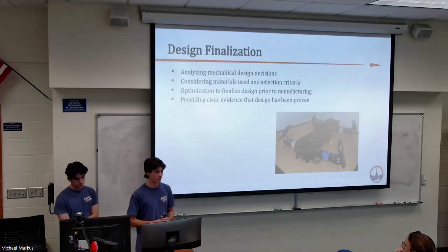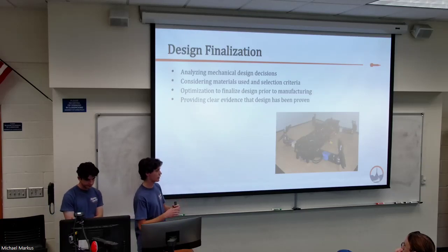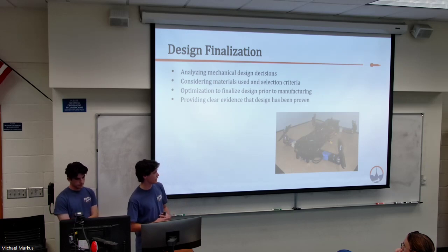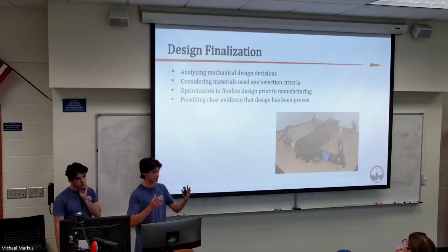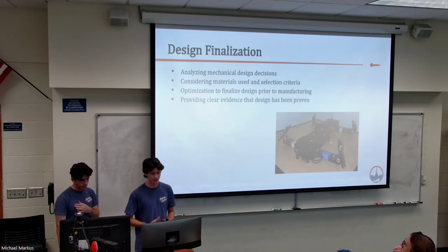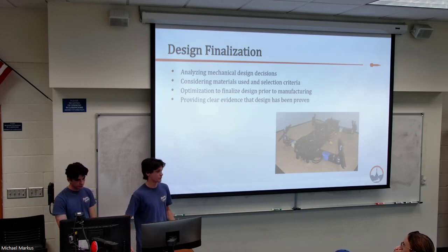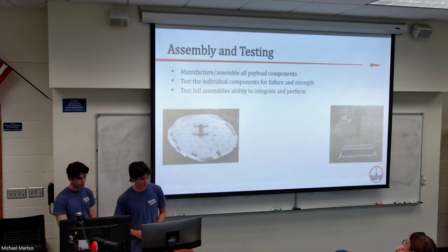And then you might think, well, it can fly when we take it off from the ground, but is it going to be able to fly when it comes out of a rocket? So you may want to do a full scale rocket flight test or maybe a subscale rocket flight test to save a little bit of money. That way, when you go to competition, you don't find out on competition day that what you've been working on doesn't actually work. So yeah, that's more with assembly and testing.